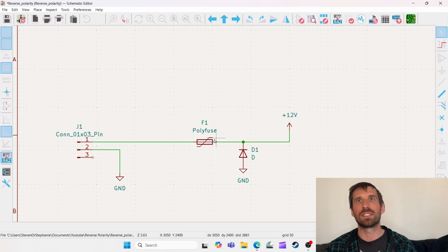I've done this and it's not my favorite. Polyfuses take a while. And the current has to be a lot higher than whatever it's rated for. But all that's in the data sheet, so you can always look that up. But also, in the meantime, whatever current is going through here, this component has to take. So it's probably got to be pretty oversized.